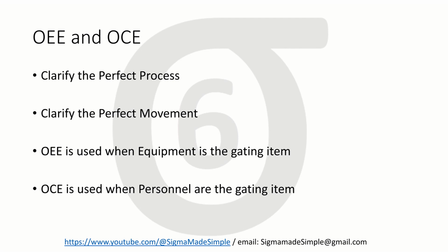Now, these are two different tools actually, and OEE stands for overall equipment effectiveness. And you use OEE when the equipment is a gating item, like an injection molding machine. It's different than efficiency. OEE takes into account availability, performance, and quality, not just efficiency. So we will go into more detail on this later. OCE stands for overall cell effectiveness, and you use OCE when the operator is the gating item. For instance, like a carpenter who uses many tools.